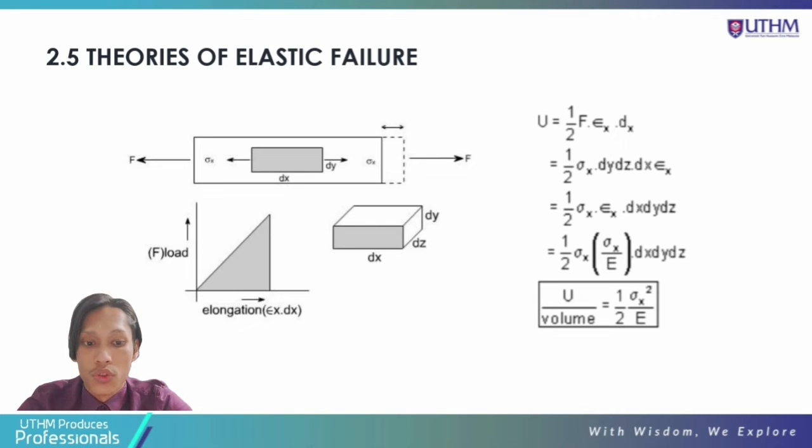The most usual test is a simple tensile test in which the value of stress at yield or fracture is easily determined. However, a machine part is generally subjected simultaneously to several different types of stress whose actions are combined. Therefore, it is necessary to have some basis for determining the allowable working stress so that failure may not occur.